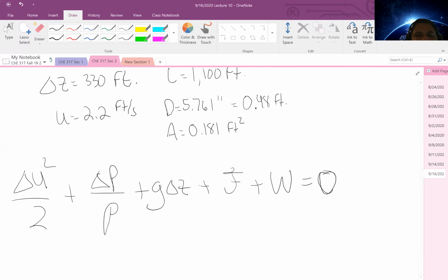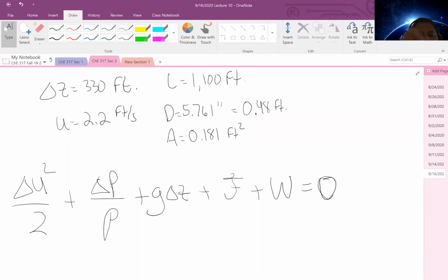So which terms can we neglect in the energy balance expression? Pressure. Yeah, I haven't said anything about pressurizing the flow. So I would consider both the starting and end pressure to be about atmosphere. And a lot of times in these types of systems, you can always work it into the static lift that you need to incorporate into the fluid.